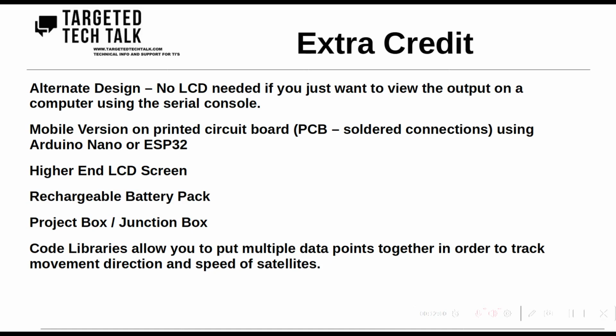So what else could we do with this? There is an alternate design here. Really, the LCD screen output can be optional. If you just want to connect this to a breadboard and your Arduino Uno, you could get the same information from the PC connection. If you run this from the PC, you could get that information on the screen through what's called the serial output. The serial console shows up within the Arduino IDE. So the LCD is not strictly required.